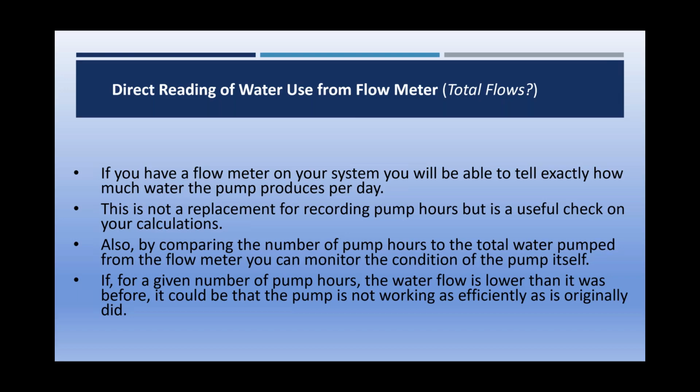Now, recording your flows off your flow meter, it's not a replacement for recording pump hours, but it is a useful check on your calculations. Also, by comparing the number of pump hours to the total water pumped from the flow meter, you can monitor the condition of the pump itself. Sometimes there can be change in the level of water in a well, which means you're pumping against a bit higher head, and that'll change the amount of output you're getting from your pump.